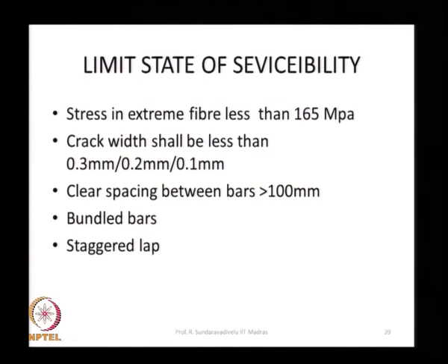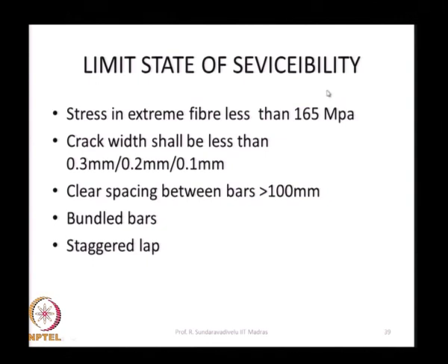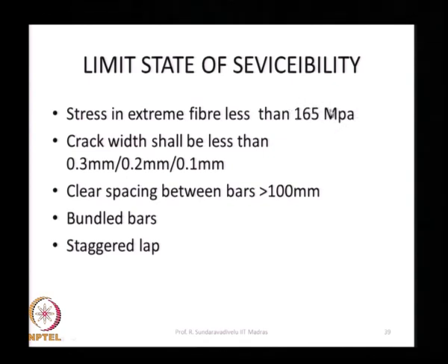This permissible tensile strength of concrete is given in IS code for different grades also, that also you can check, that may be somewhere in the range of this modulus of rupture only, and that value you compare with this. So, the tensile strength of concrete is much less than the tensile stress in steel. So, the concrete will crack in tension. So, we have to neglect that concrete, but when it cracks there is some crack width.